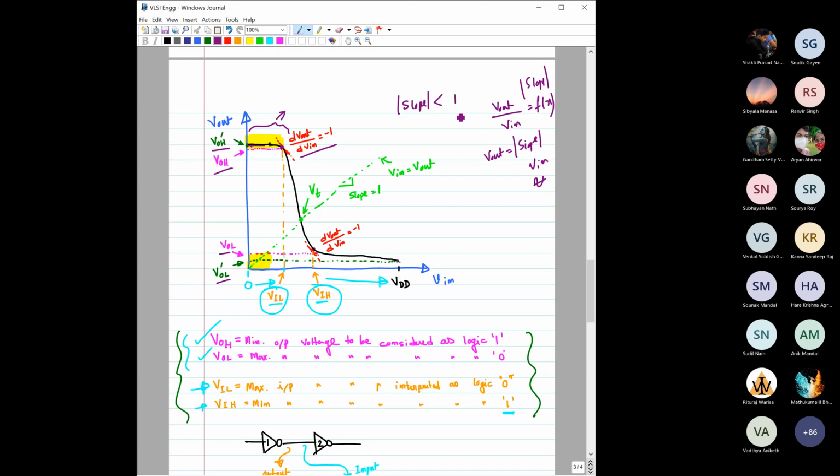if the slope is less than 1, that will be reflected less on the output side, right? But if you are crossing this point, then that would get amplified. It means any noise coming within this range would be reduced. Does that give some idea why you are choosing -1 to be the limit? Yes, sir. Okay, great.